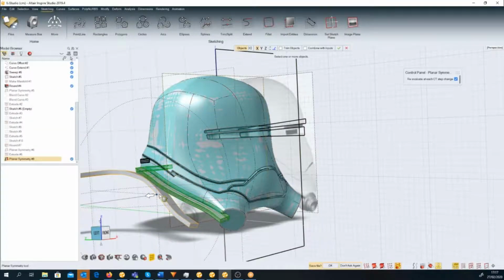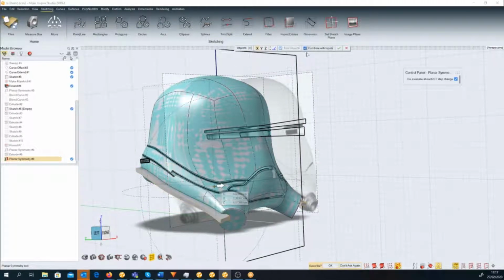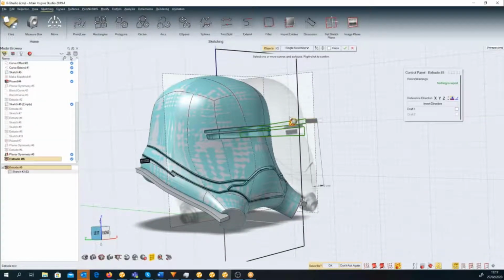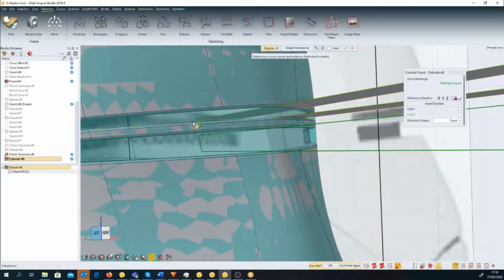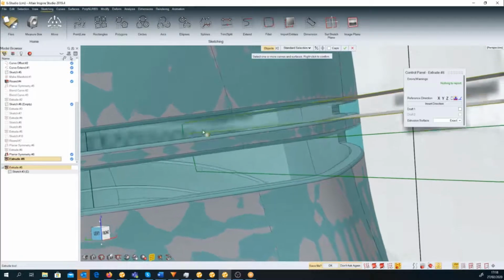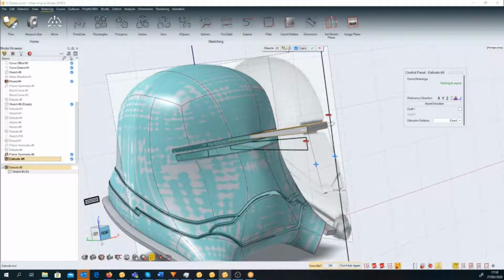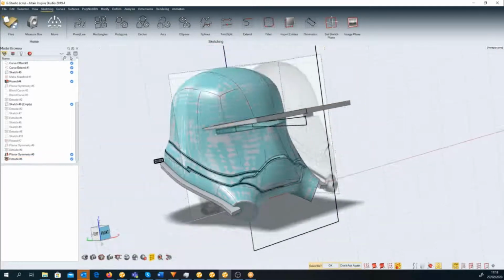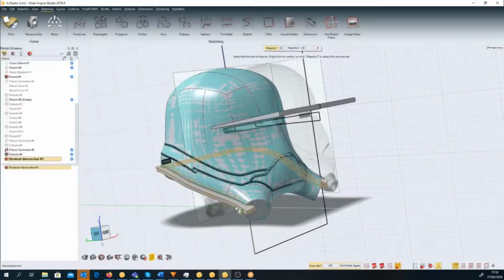Those geometries are necessary to create the missing covers on the bottom part of the helmet and over the ACE area. In the first case, I'll need a planar symmetry, and in the second, I'm going to create an extrusion from some sketch geometries. By a Boolean intersection between these three solids, the covers will be done.